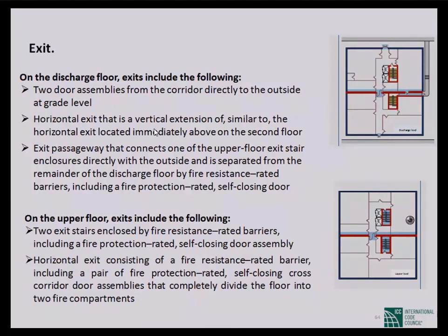Again I repeat, if a spiral stair is used for a fire rated stair, the maximum population will be 3. If it is more than 3, no spiral stair can be used as a fire stair. So in each corner there is a spiral, but that is not a fire stair.